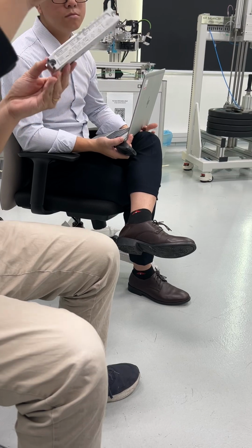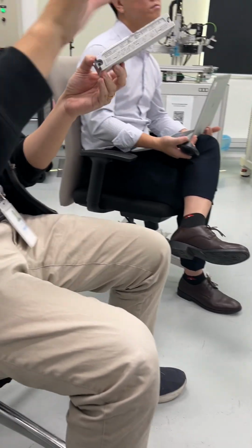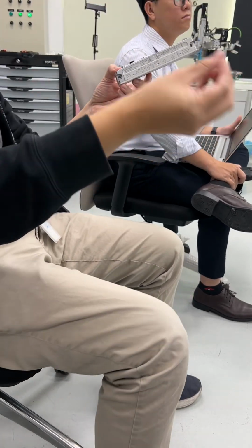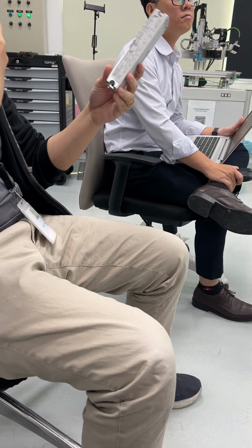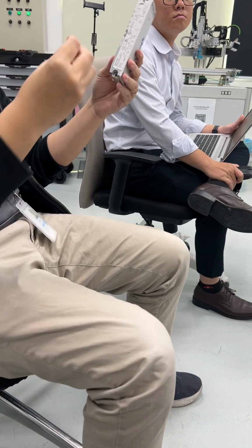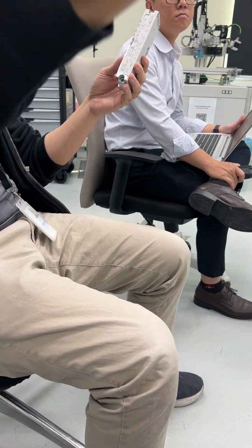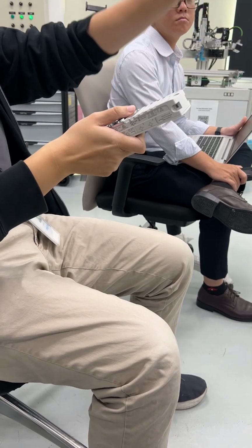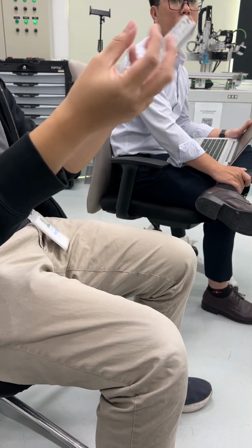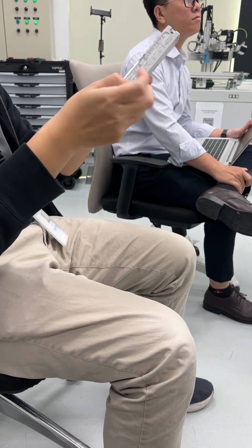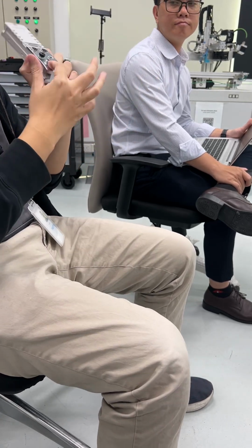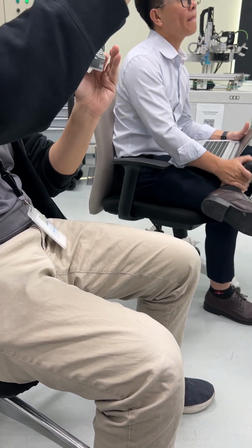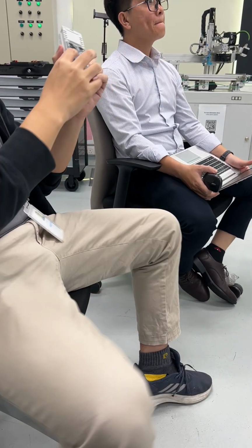So the good thing about this is that it's flexible. You can easily have different power zones, because sometimes our customers want a power zone. For example, they press emergency stop on this and just want to cut off the power for these sections of the IO modules, and the other section they don't want to cut off, it can continue. So with this, they can easily achieve the power zone. I think it will be mentioned in the slides later, but since we are here now, I just talk about it.